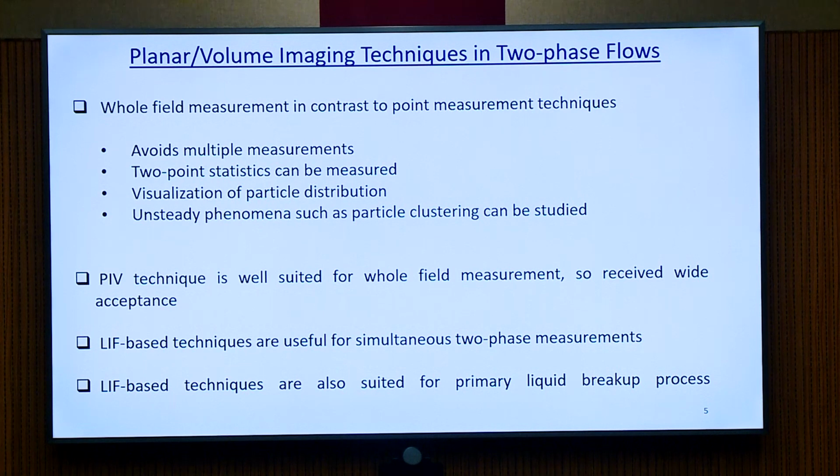These are intrusive techniques. As far as non-intrusive techniques are concerned, we have also laser Doppler velocimetry or phase Doppler anemometer, PDPA, where measurements are taken at a point. Now, the whole field measurements have some advantage with respect to the point measurement techniques, that it avoids multiple measurements.